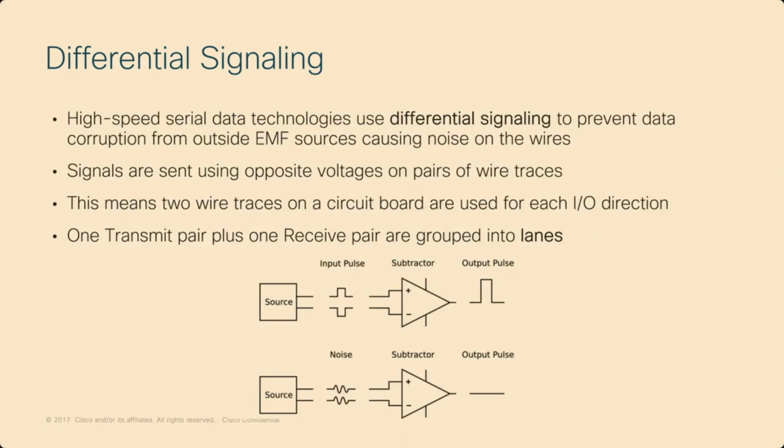So when I'm making those connections, we are using what's called differential signaling. And that means that we're actually using 2 wires to send the signal, and we are using positive voltage and negative voltage on the two different wires in order to create a pulse that is different in each direction on each wire, so that any kind of noise that might spike and add interference and add voltage to that line is not interpreted as a signal. It has to be a positive on one side and a negative on the other in order to count.